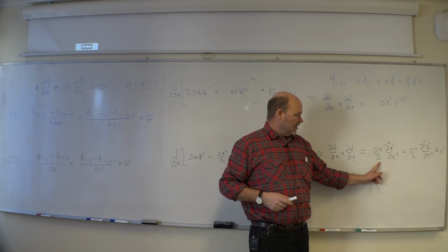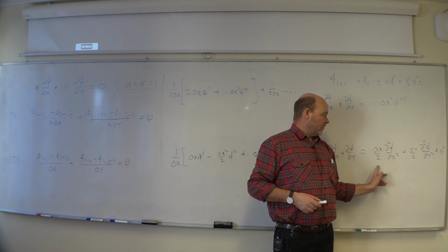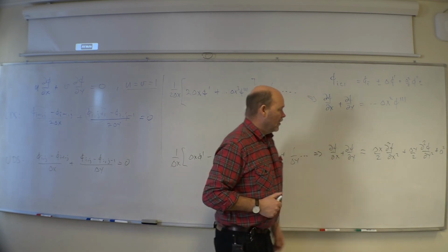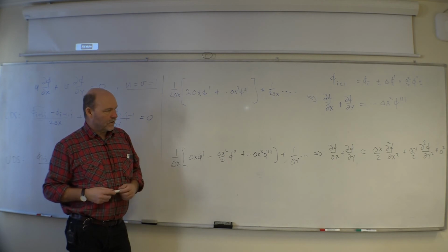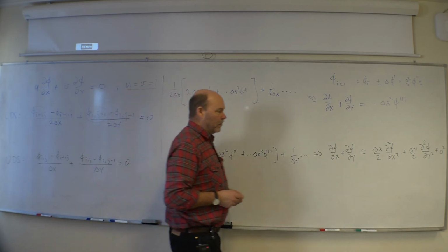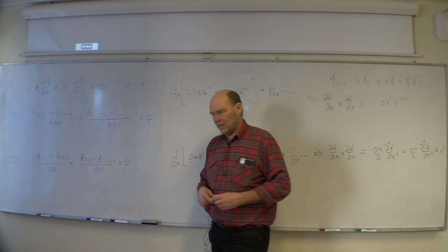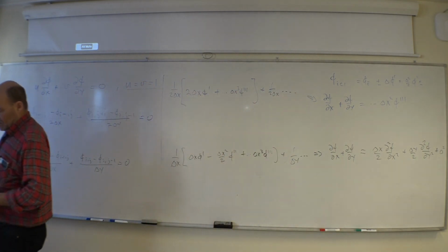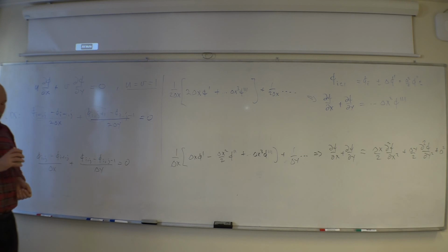And yes, if you have very small delta x's and delta y's, this false viscosity, actually here I called it artificial viscosity, is going to be small, but is still going to be present. And as you know, even small diffusion coefficients give rise to a lot of problems. So the modified equation is actually a very good tool to see what's going on. It's really recommendable.